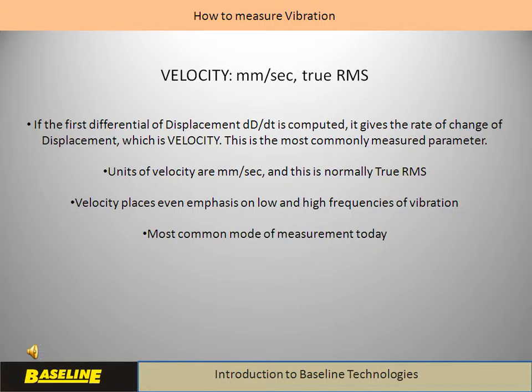The rate of change of displacement is velocity. It is the first differential of displacement with time. Therefore, velocity is the most commonly measured parameter as per modern standards. Velocity is the best representative of the energy of vibration.